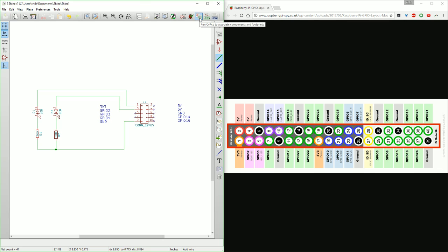Now, I'm going to take a quick break here and talk to the camera. This seems a little bit complicated so far, but we're doing pretty well, right? So what we're doing is we created a schematic notation, which is kind of a symbolic representation of what we want to have in the schematic. Now what we need to do is connect that symbolic representation to the actual real world, whatever we're going to solder to when we have a board, right? And so what this does is it connects the schematic symbols to the layout footprints. And so that's the level that we're doing now.